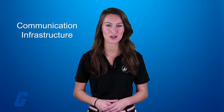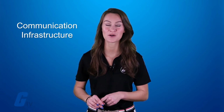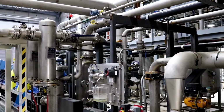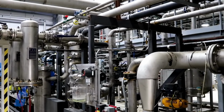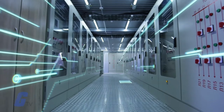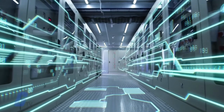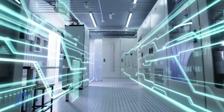Finally, the communication infrastructure delivers connectivity to the supervisory system and then to the RTUs and PLCs for the user to command. The communication infrastructure is necessary to relay data from remote RTUs and PLCs, which run along electric grids, water supplies, and pipelines. Communication is the absolute most essential link for a SCADA system to operate properly. However, how well the system manages communication from HMI to RTUs and PLCs fundamentally determines how successful a SCADA system can be. SCADA systems are crucial for industrial organizations since they help maintain efficiency, process data for smarter decisions, and communicate system issues to help mitigate downtime.